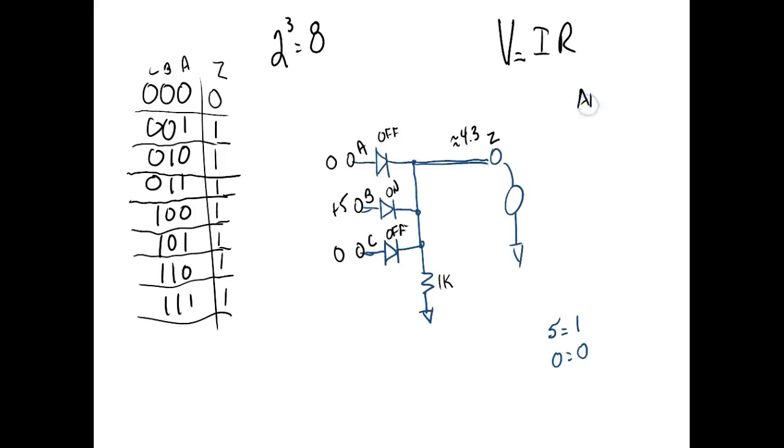So what logic do you think this is? Is this AND or is this OR? I can't do NAND and OR with this yet. We can't pick up a NAND and an OR until we pick up another device. So this is an OR. This is an OR gate. So if A is high, or B is high, or C is high, we get a high. The term we like to learn is "any." If you use the term any, that's OR. So any high gives me a high.